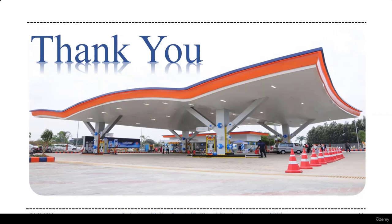Pinned base gives an economical footing. In any steel structure, pinned base will give an economical footing. Yes, temperature load combinations are also there, you can see. If it is a PEB with a crane, what is the base support condition? No problem at all. If a crane is also there, we have to check for pinned base condition only. If the sway is not controlled, we have to go for fixed base.